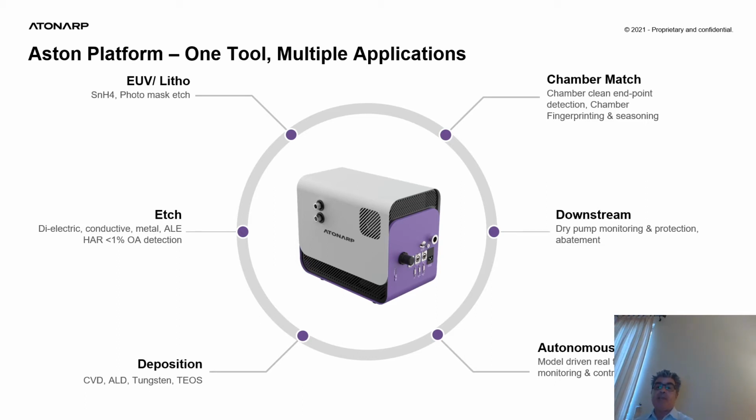industry, including in EUV, where keeping the optics and photomask clean from debris and contaminants is critical to maintaining a high laser conversion efficiency. In etch, the pain points are low open area percentage, under 1%, even lower than that, high aspect ratio, over 100:1, endpoint detection in dielectric, polysilicon, and metal etch, especially for small interconnects such as contacts and vias. In CVD ALD, ensuring film uniformity in 3D structures through endpointing on layer by layer deposition transitions.